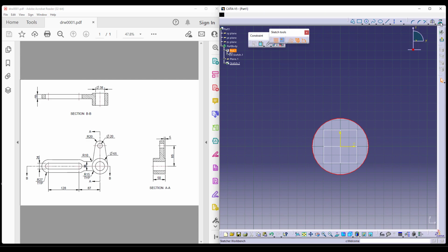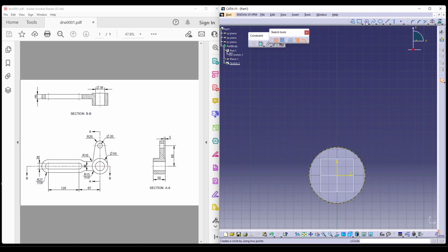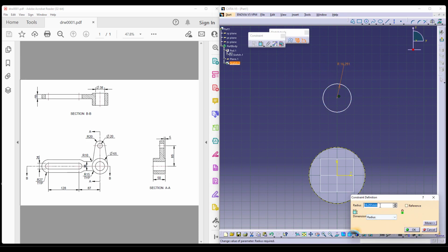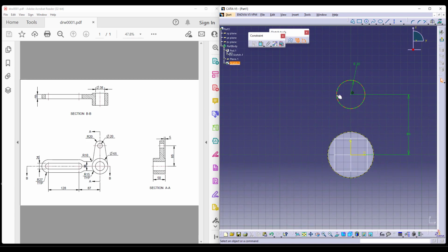This is my reference. I am projecting my reference and starting to make our body which is over here, which is R20. Let me take a circle of R20 and then later trim off the unnecessary edges. This is supposed to be a radius of 20. Now this is at a distance of 85 from the center, so this is supposed to be 85. Now continuing this, the slant line should be joining the slot here which is joining the straight lines.